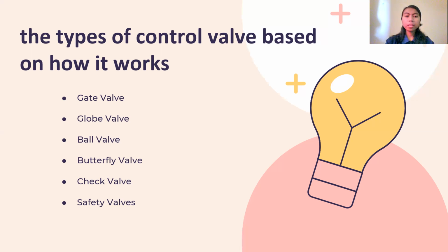Ball valves are widely used because of their ease of rapid operation and ability to withstand high pressure and temperatures. Depending on what material they are made of, ball valves can withstand pressure of up to 10,000 psi and temperature of around 200 degrees Celsius.